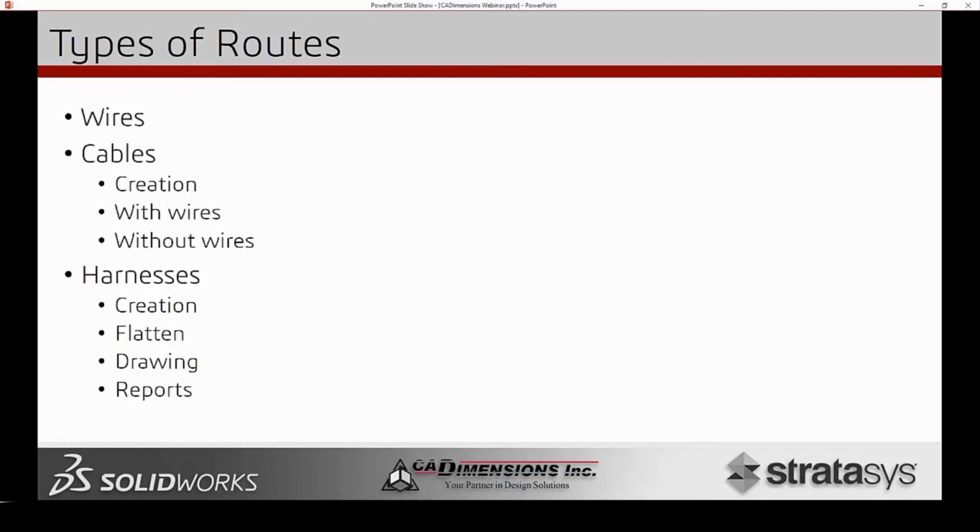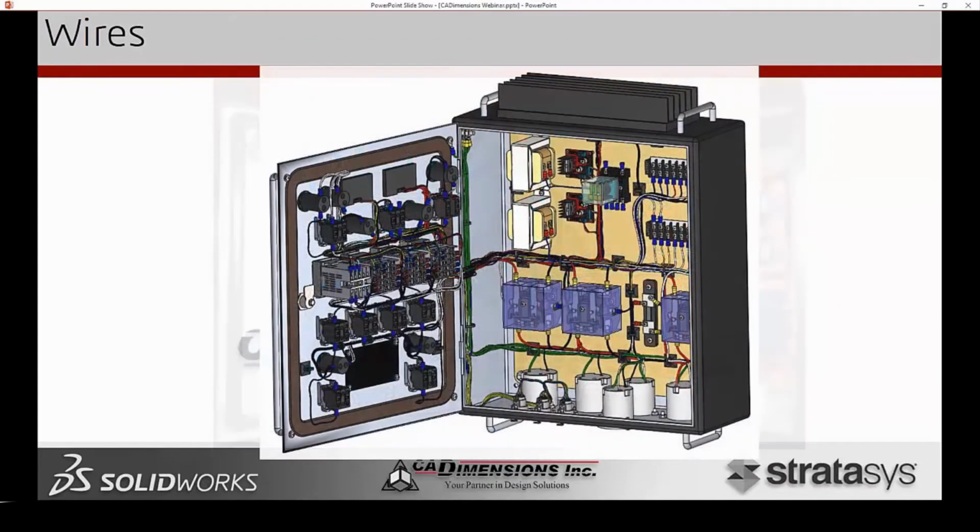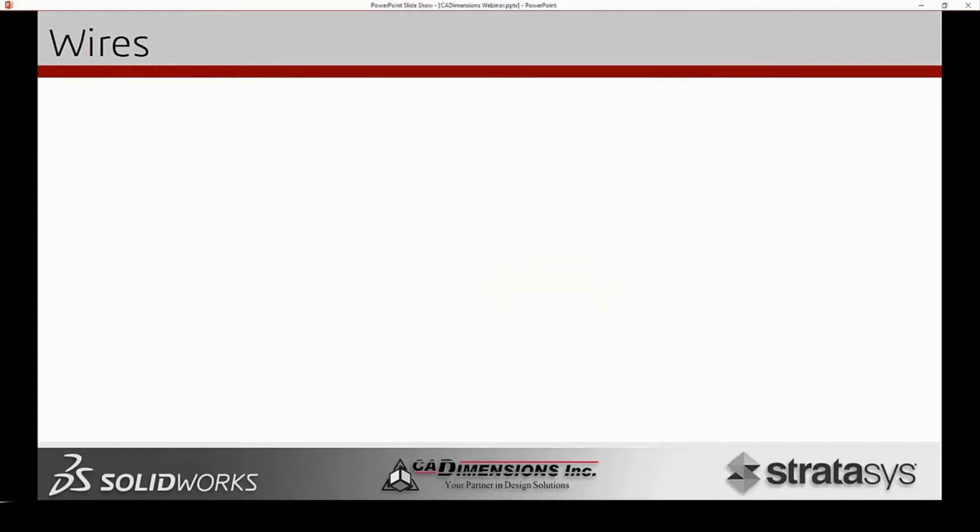So starting with wires, we can see in our example here that our panel box is going to be pretty much full of wires. We'll have terminals or termination points that will run into each circuit breaker or relay, as well as our terminal block. And we want to be able to route those wires as a point-to-point connection. Inside of SOLIDWORKS, we know we can make this panel box, we know we can make these connectors. It's a matter of how we get those wires to show up accurately to what we're designing.